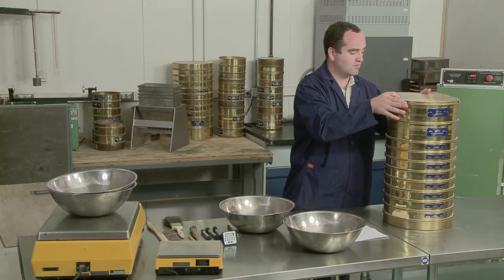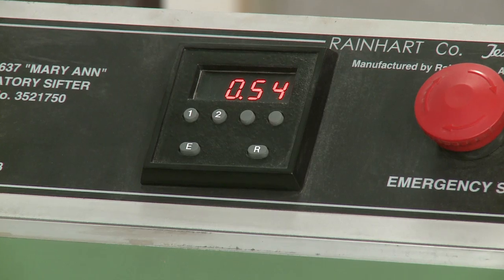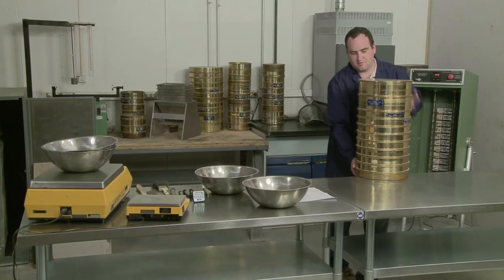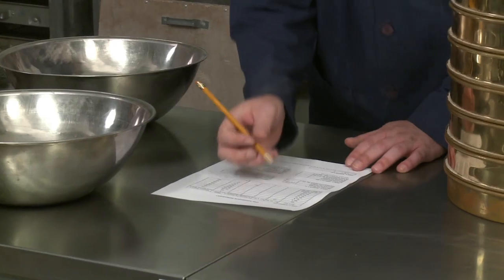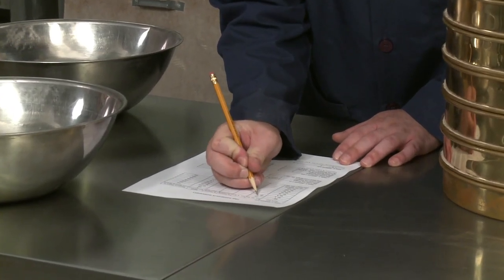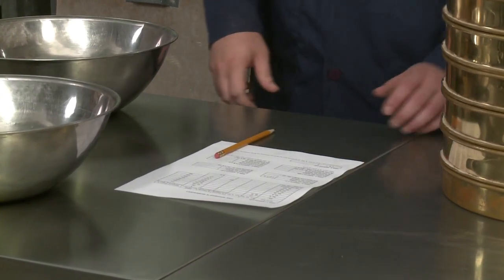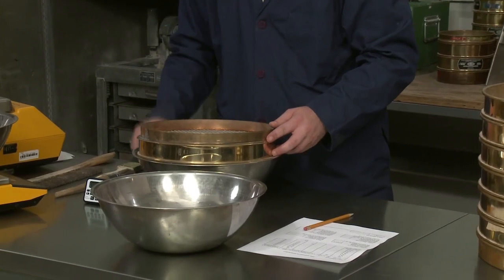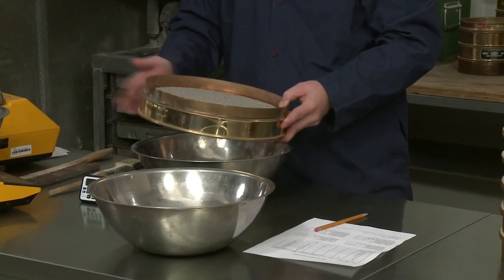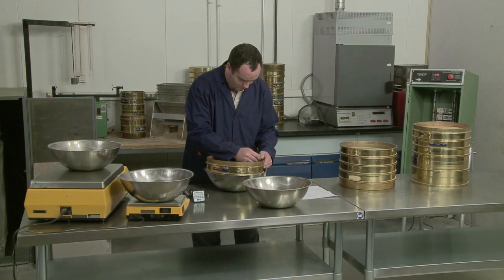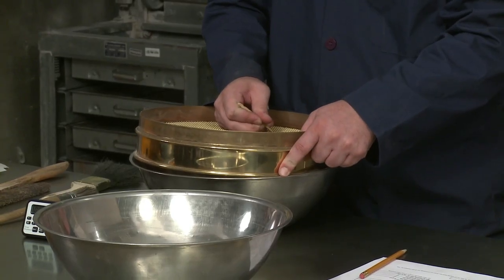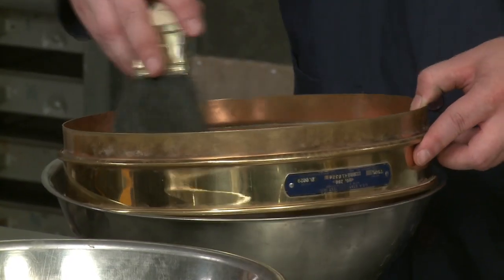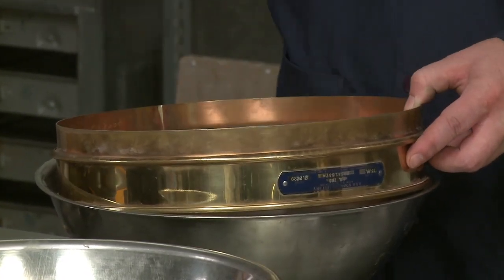Cover the top sieve and agitate for a period of time that meets the requirement for adequacy of sieving. When the sieving procedure is complete, record the accumulative weight of the material retained on each sieve. Remember to check each sieve for blinding and make sure that all material is transferred to the weighing container. Use a rigid instrument to remove lodged particles from coarse sieves. On finer sieves, use a brush that will free the particles without causing damage to the mesh.